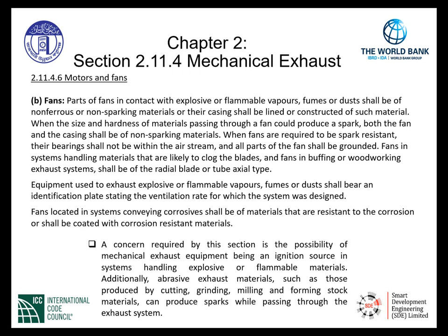Moving on, it indicates that fans in systems handling materials that are likely to clog the blades and fans in buffing or woodworking exhaust systems shall be of the radial blade or tube axial type. Further, equipment used to exhaust explosive or flammable vapors, fumes, or dust shall bear an identification plate stating the ventilation rate for which the system was designed.